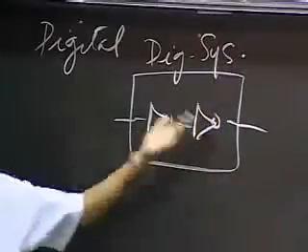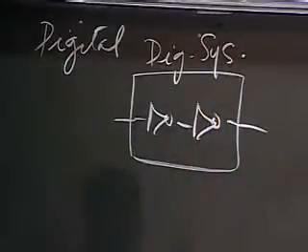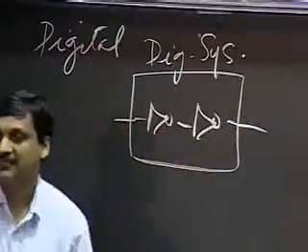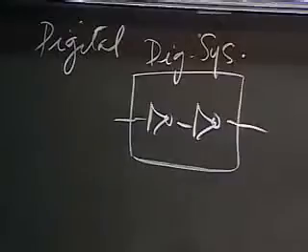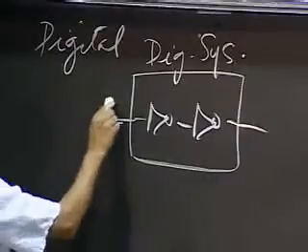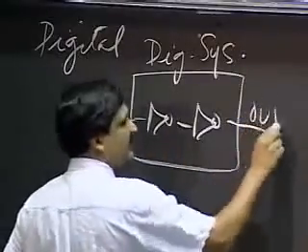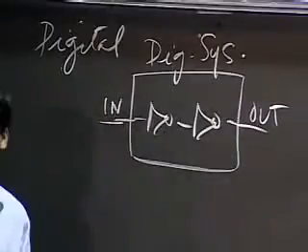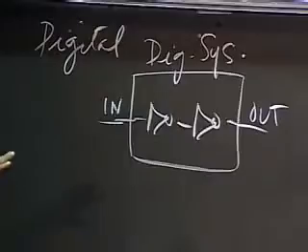And this system simply contains a pair of inverters. So if I send a 1 here, it's a 0 here and a 1 here. It's a very simple, trivial digital system. And here's the input. Here's the output. And we said that for digital systems of this sort to work, they have to follow a static discipline. Okay, our signals and our circuits must follow a discipline for them all to work together.